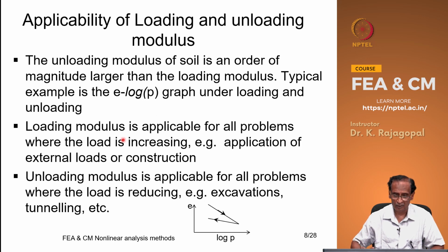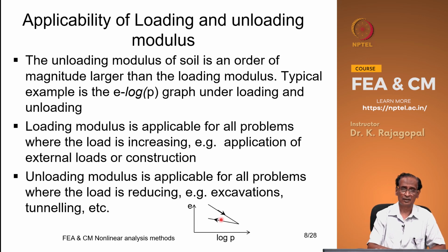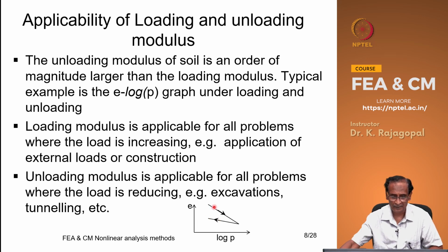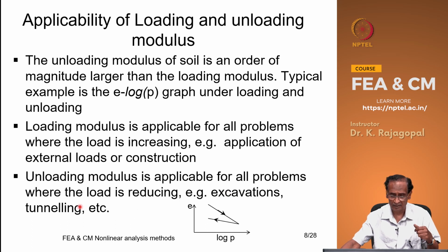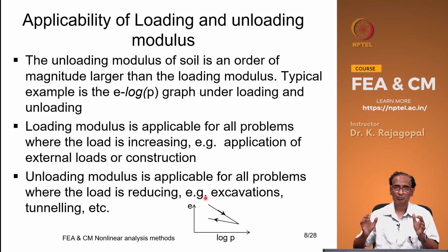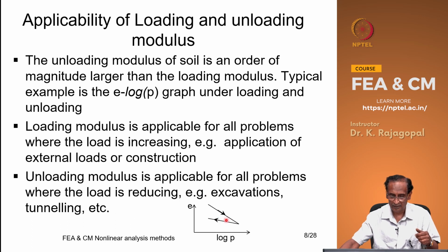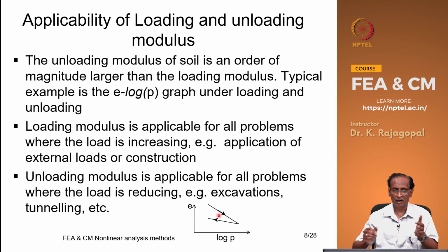But then the unloading modulus is the slope of this unloading part of the stress strain curve or the E log P graph, that is applicable for all the problems where the load is removed, that is excavations and then tunneling and so on. Okay. So, if you have any deep excavations, we prefer using some other modulus during the unloading part, because if you use a normal loading and unloading modulus the same, you might over predict your deformations.